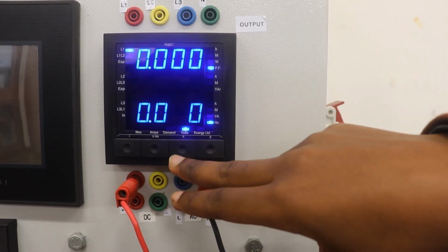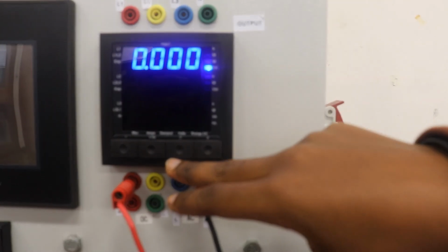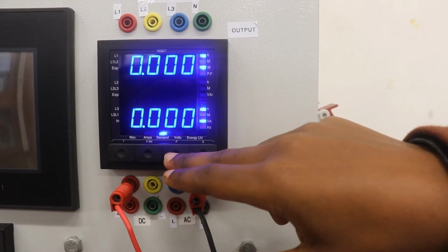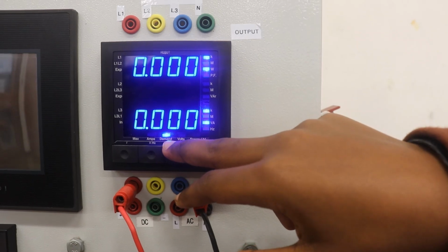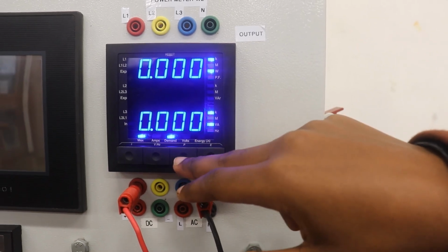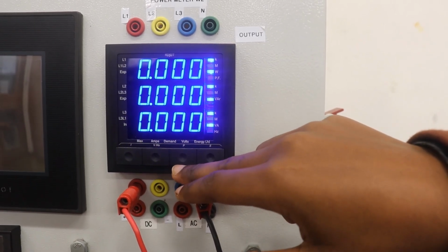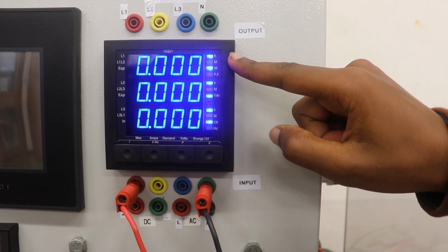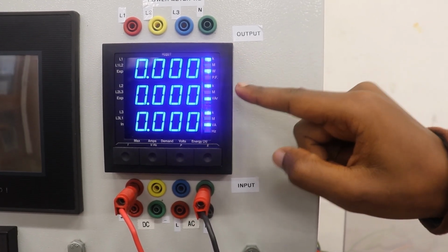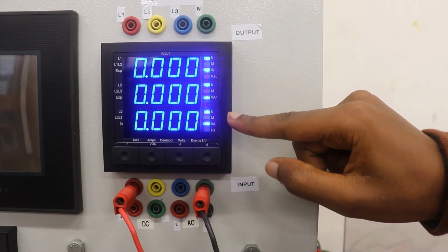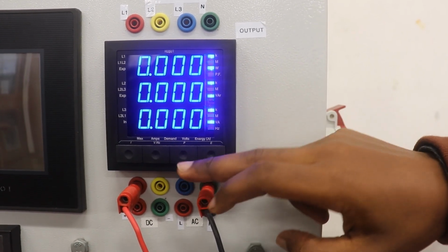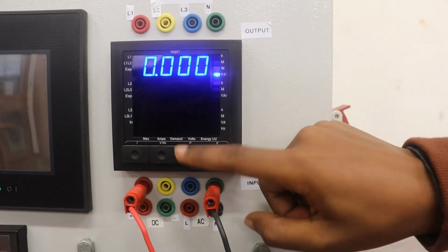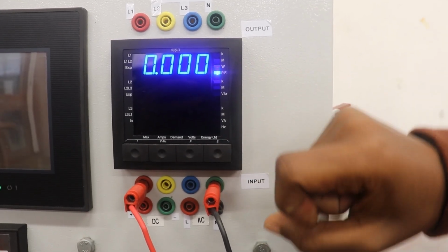And moving on to the power readings, this also is quite similar to the current, where we're able to measure our demand power, maximum demand power, as well as our RMS power units. Please note that we are able to see our real power, our reactive power, as well as our apparent power from this power meter. We can also measure our power factor by using the same third button.